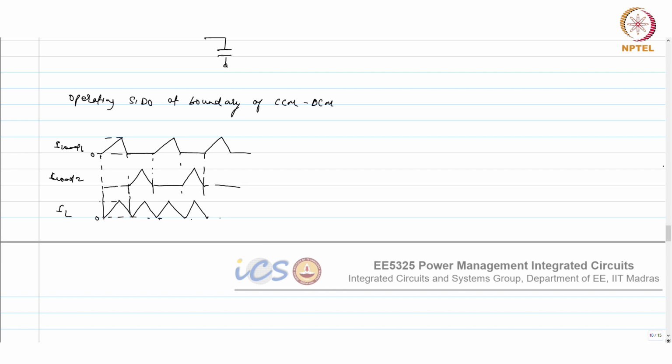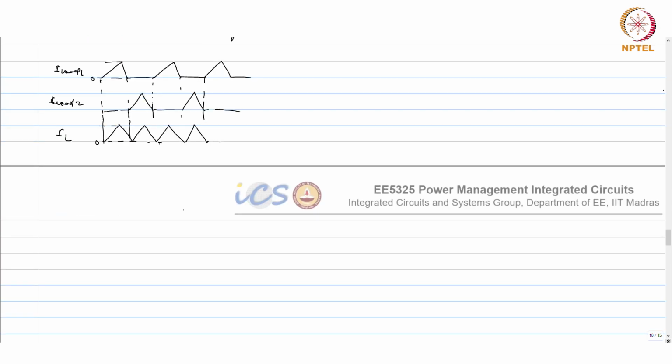If you are not concerned about the switching frequency, then it's fine and you can always keep the inductor current continuous. It's similar to the constant on time we were talking about. As soon as it goes to 0, you trigger the next phase, and that will be coming from your control. The on time will be decided by your V control. Say you're comparing a ramp with the V control, that will generate the on time. So that on time will vary, but it will always get triggered at a zero current information.